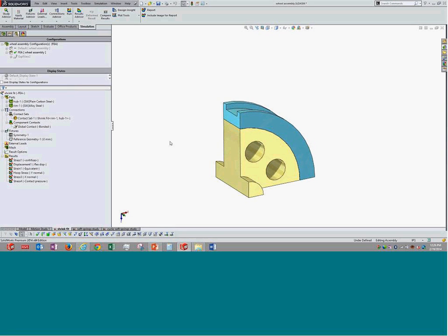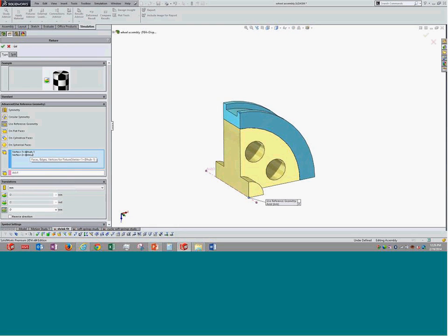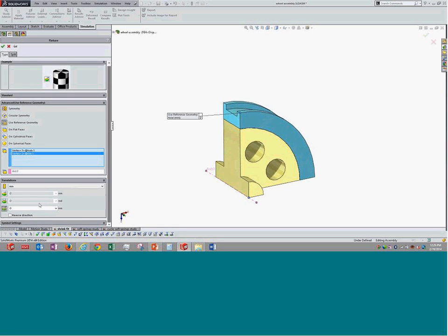So it is a kind of instability. To avoid it, we take a few vertices away from the place where we are going to apply forces or loads, and those vertices can be used for resting the body and avoiding it from flying off.